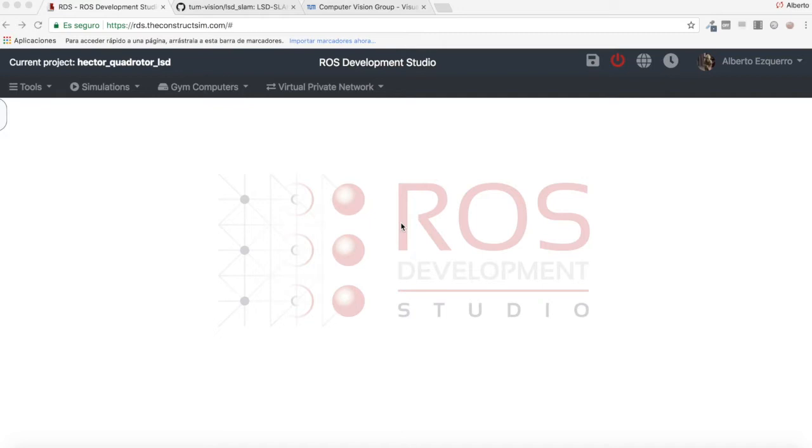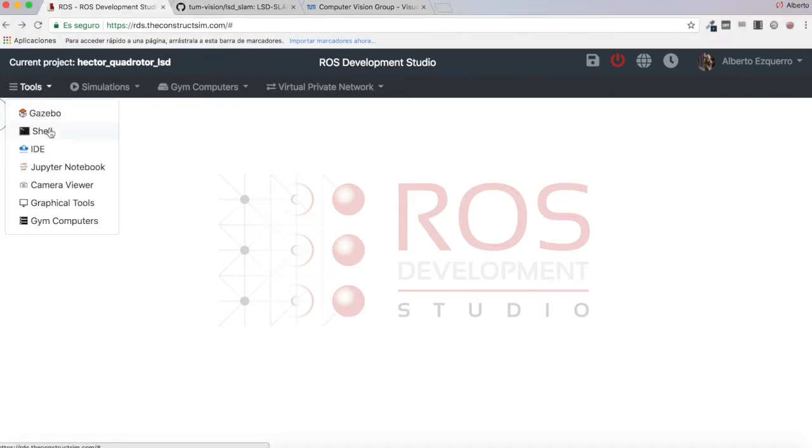In this case, this is the fourth video of this project I'm doing. Let's see if finally this is the last video and we can achieve to perform LSD-SLAM correctly with a drone. If you remember from the last video, we were trying the LSD-SLAM packages with a Hector Quadrotor simulation, which we managed to have working. But we had a problem with the location of the camera. We were having some noise there because it was capturing part of the drone, which would lead to errors.